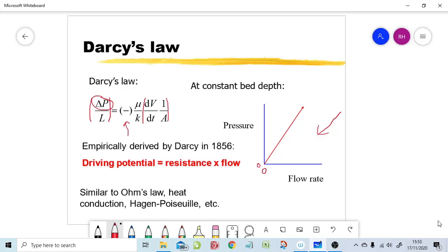However, if doing a derivation, if adding other equations to this, then that minus sign can be very important. Otherwise, the derivation might not be quite as robust as it should be. I mean, Darcy's law is such a simple linear equation. It's hardly surprising that it was observed a long while ago, in 1856, by Darcy looking at the flow of water through filters outside Paris.